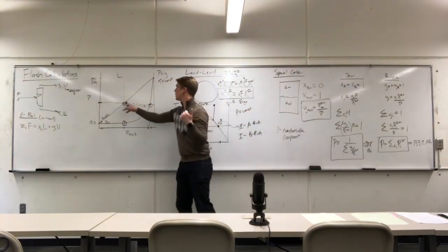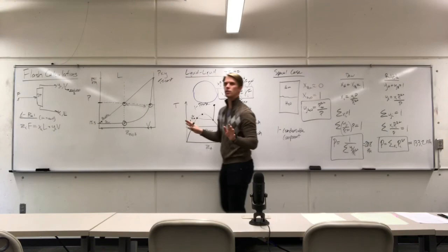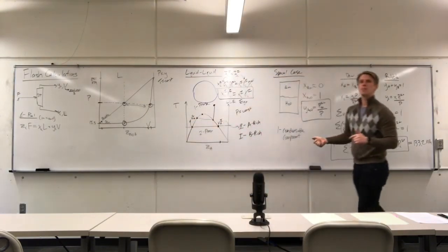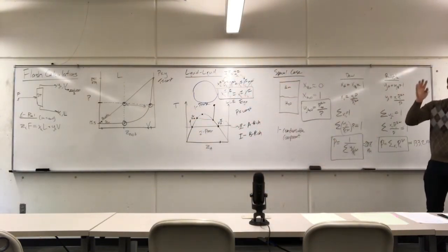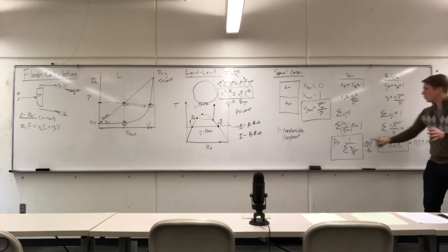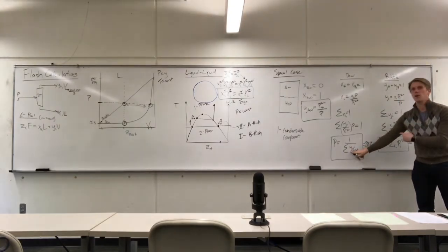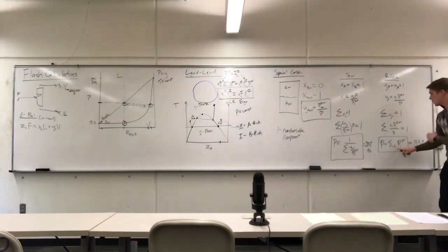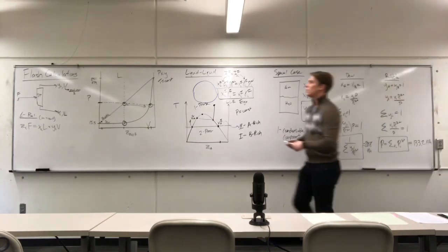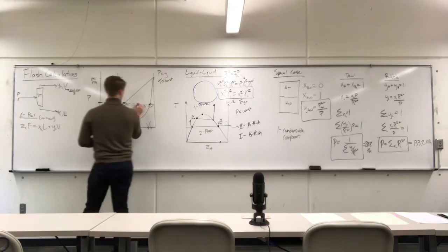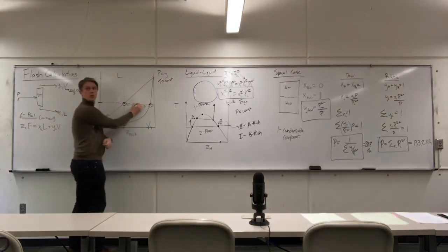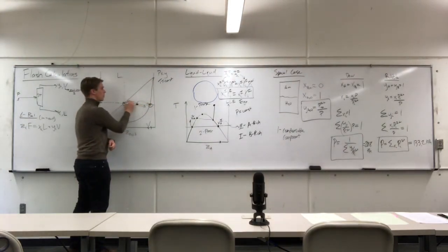For the 2-phase region, you can use that equation throughout. Same thing with the dew curve. It only becomes the bubble equation, it only becomes the dew equation, when I assume that I know what the vapor composition is, or when I assume that I know what the liquid composition is. But if I were to tell you that you're in the 2-phase region right here, both of those equations are valid. One would give you this point, one would give you that point.